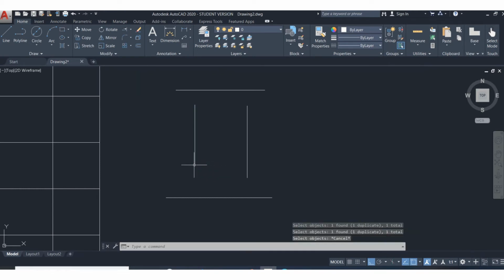It's not going to work. That's not the way this software works. Some CAD software will work that way. What you have to do first of all is choose the target. So for example, if I want to extend this line up to here, I have to choose the target line. Now it's still asking me because I can choose other targets.